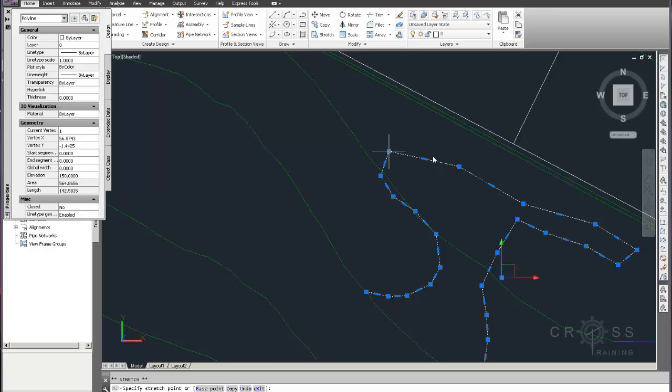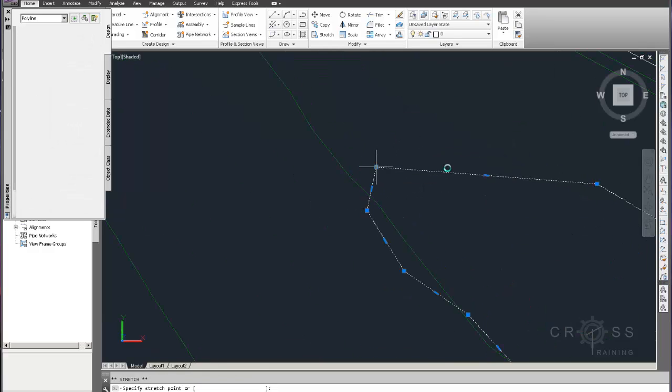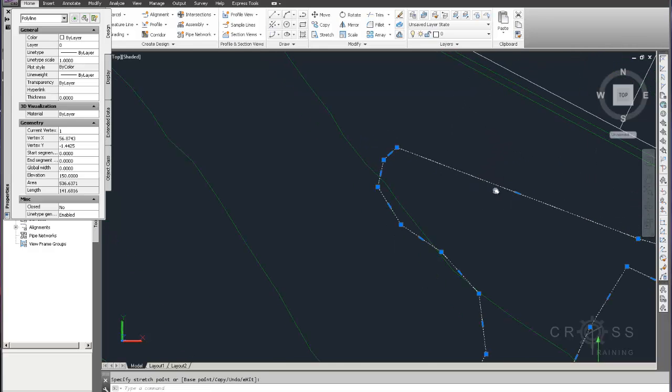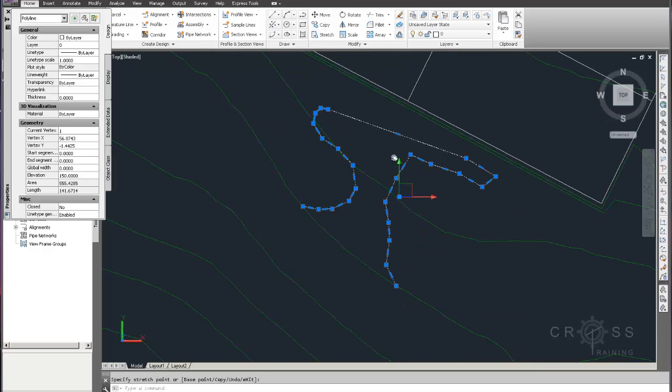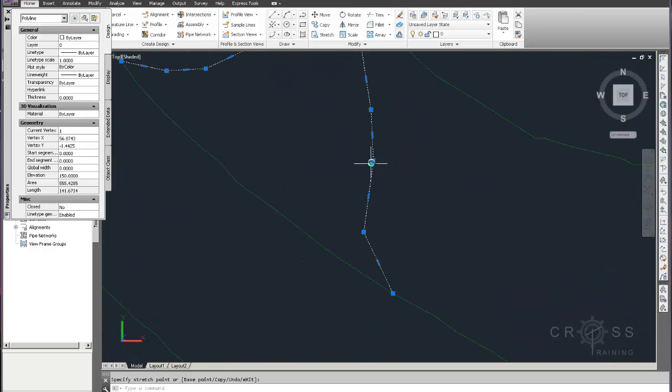So it doesn't drain into the back of your house. And that way your foundation wall isn't always soaking wet. Okay. And then I need to do something very similar to this side too.